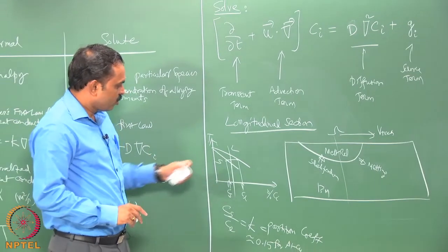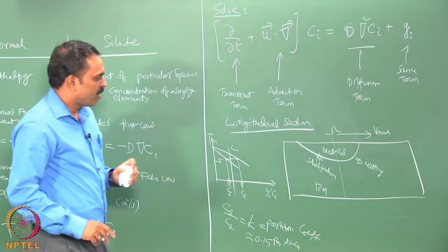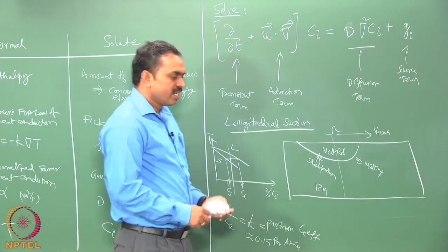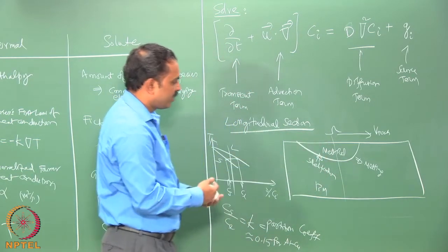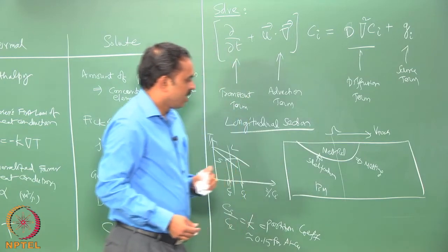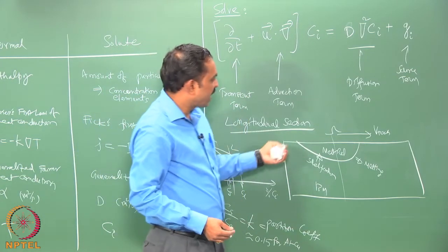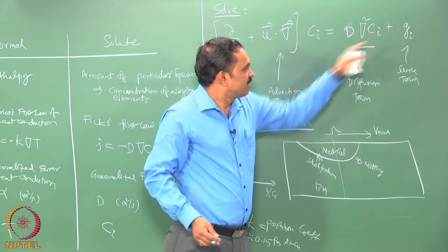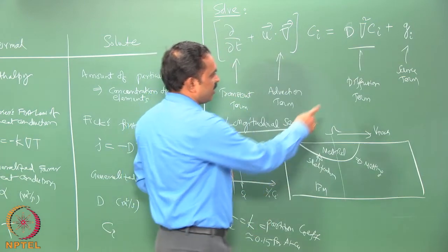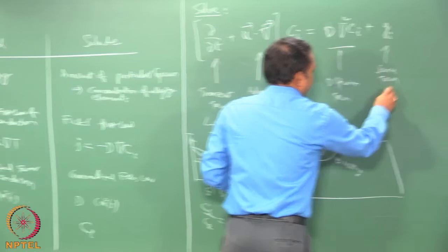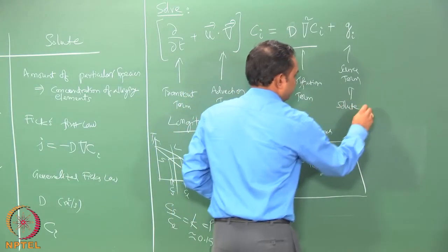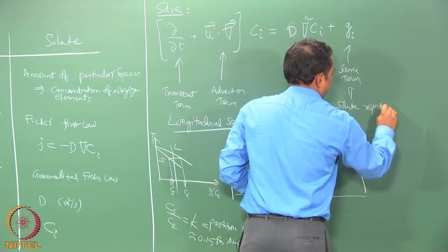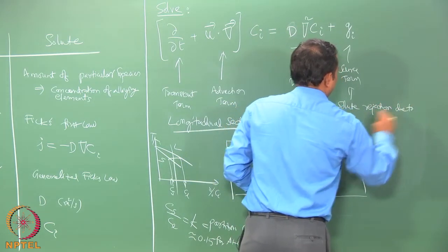So, because of this partitioning effect, then what happens is that on the solidification front some amount of solute will be dumped into the liquid pool, and that would have to be taken care as a special condition. So, if you like you could actually take that into the special term or source term here. So, one possibility is the solute rejection due to partitioning,